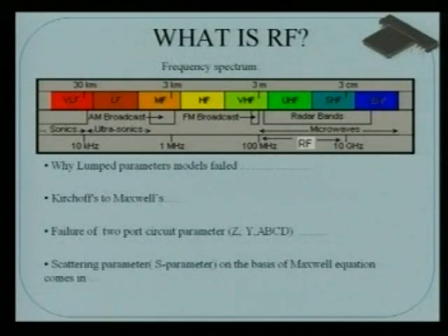Where the assumption is, if you look at even the exponential devices, suppose transistors or square law devices, this is called your first order, you are taking the first order approximations, and you are only considering signals which are very low, that is low or small signal, and the frequency is not so high. Then your lumped parameter model is valid when the wavelength lambda is very, very high compared to the component size.